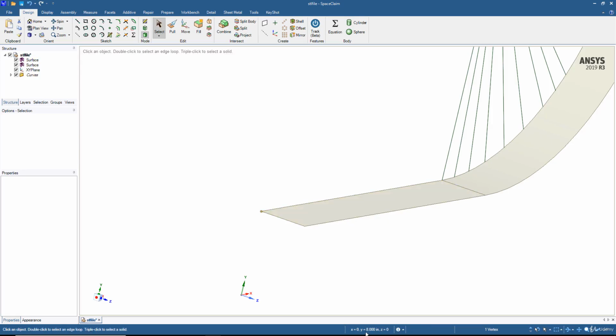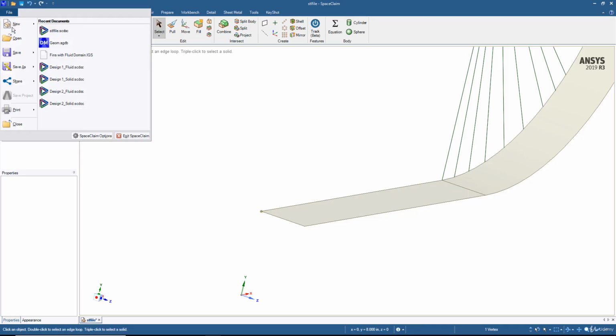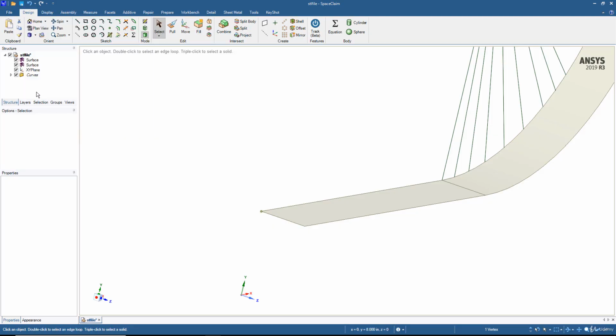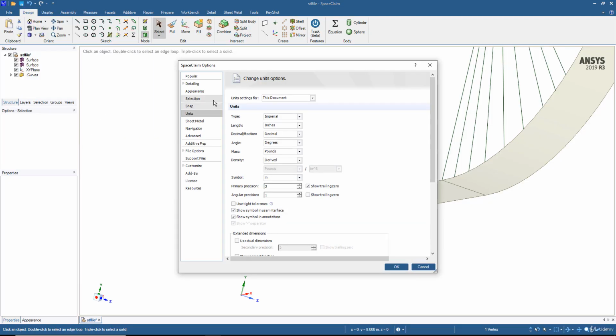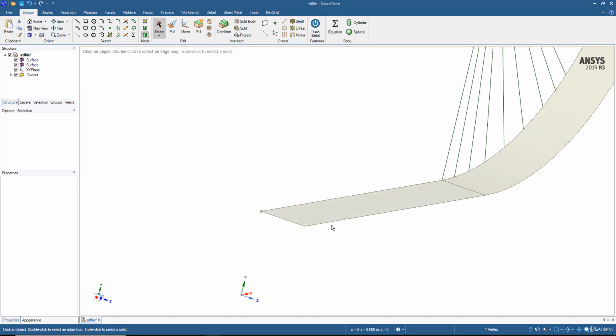And you can see that we have the line at x equal to 0 and y equal to this much. Also make sure that the units should be in millimeters, because in CFX or CFD-Post, the geometry has the units in millimeters. And because they have been converted directly from within the software to the other software, it means that we should be using millimeters instead of inches.